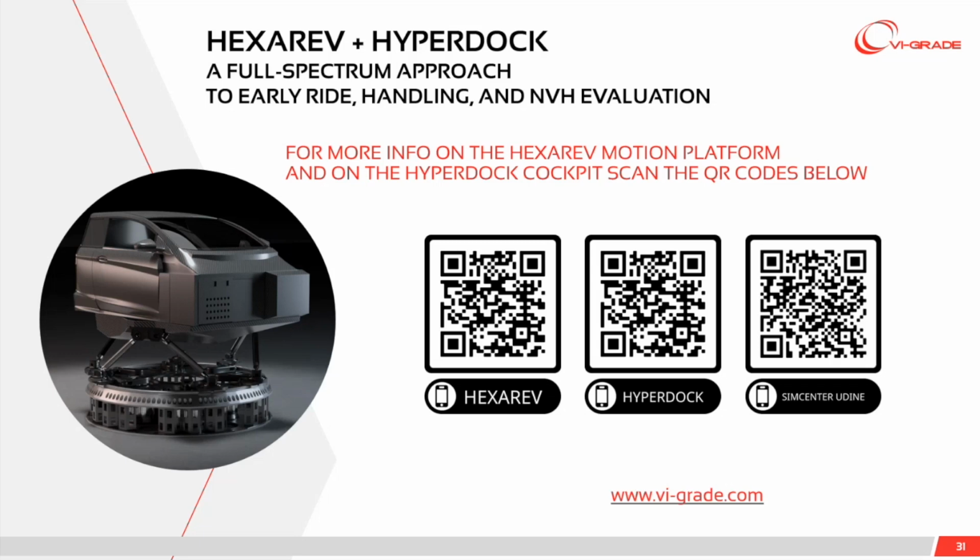In this case, of course, the suspension stiffness, all the bushings and all of these things are contained within those transfer functions. If someone wants to evaluate different bushings, that would mean that you would need to change the transfer function.